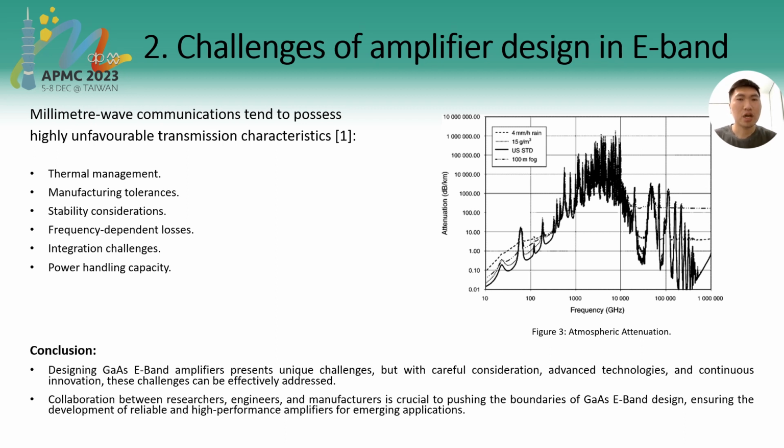The fifth challenge is the integration challenge. Integrating various components into a compact E-band amplifier can be complex due to the small wavelength involved. The solution is utilizing monolithic microwave integrated circuit (MMIC) technology for better integration and employing electromagnetic (EM) simulation tools for accurate design and optimization.